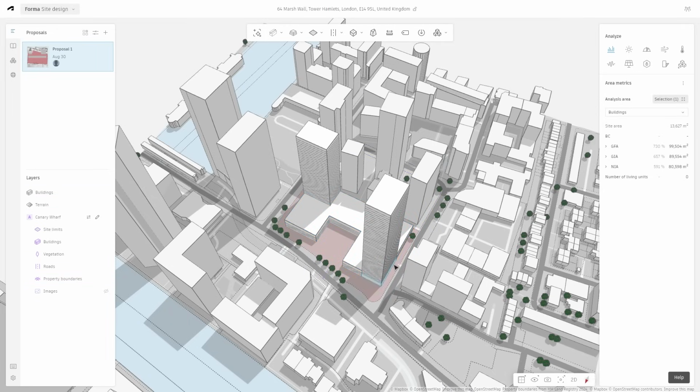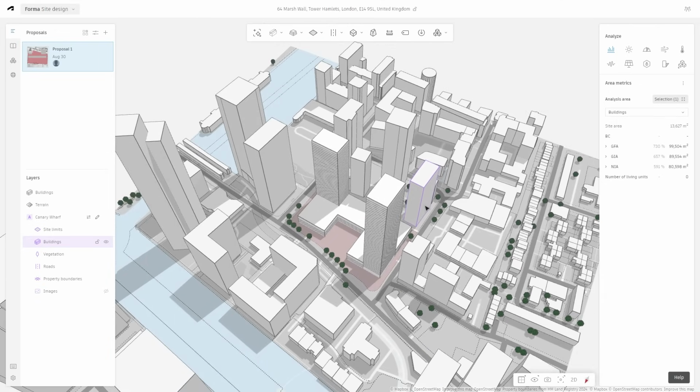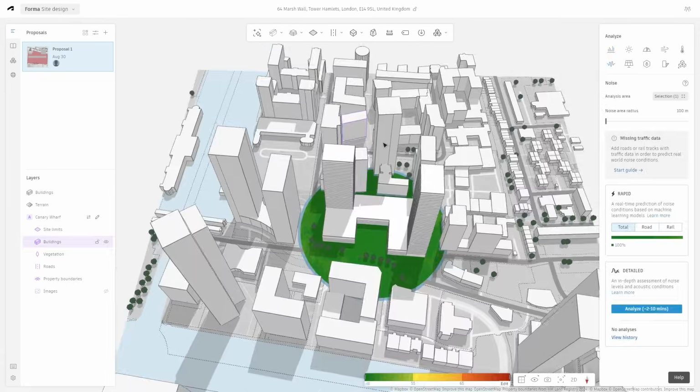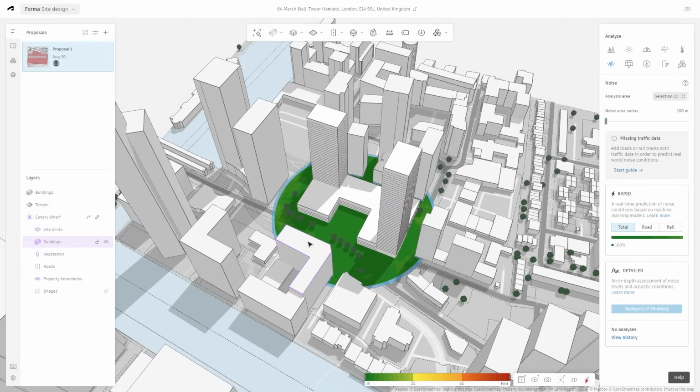A few things have also changed here in Forma, for the good of course. So now we can much faster access any important tools to create volume, surfaces, roads, terrain, and so on. But even adding extensions is a bit more accessible here. Now, I really love that Forma has implemented a noise analysis. It's something I really looked for in many other software packages, and it's pretty much the first one I have encountered, and it's also super easily accessible. All analysis tools are just here on the top, and the pictograms speak for themselves, and you can just pick out noise here very easily. Now, if I click on this, it does a very rapid noise analysis. Nothing really happened here. Everywhere is 0 decibel. It's absolutely quiet.